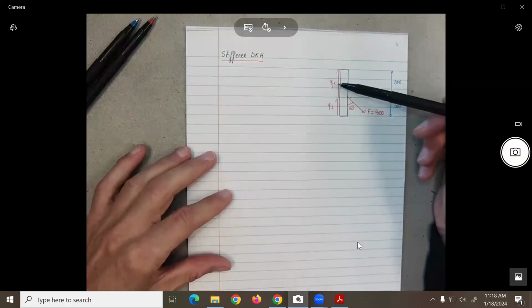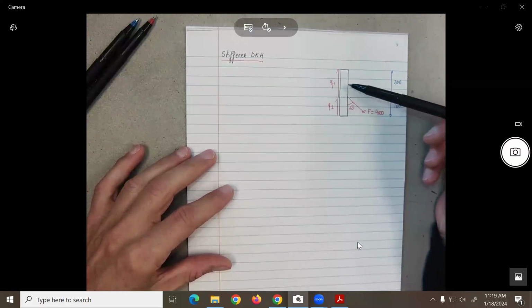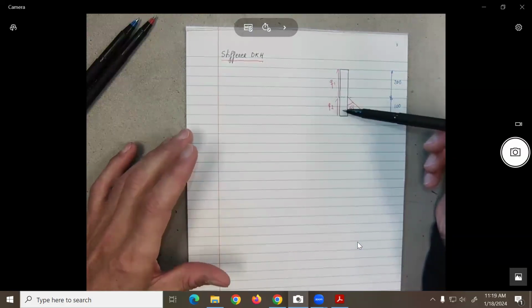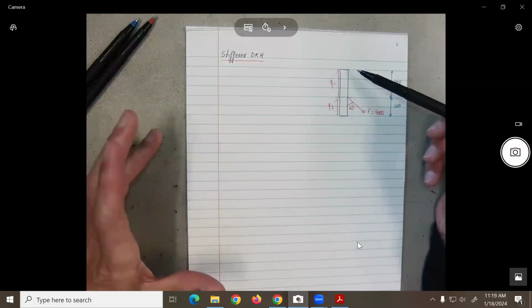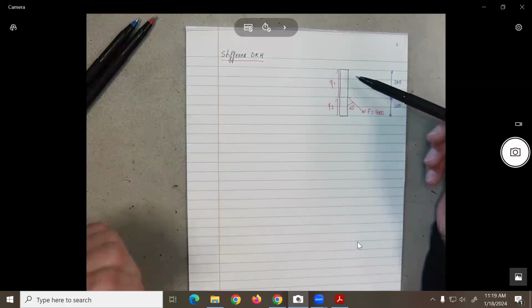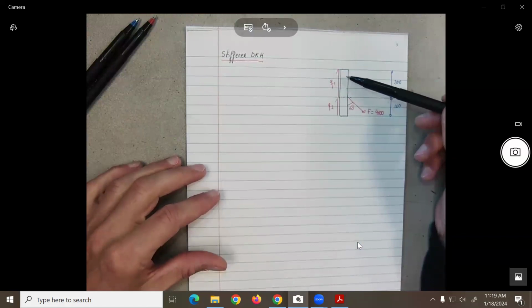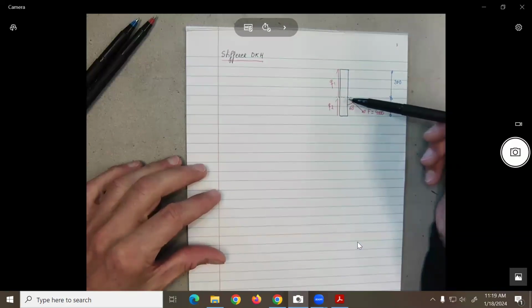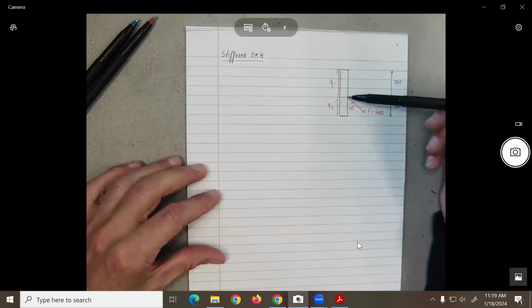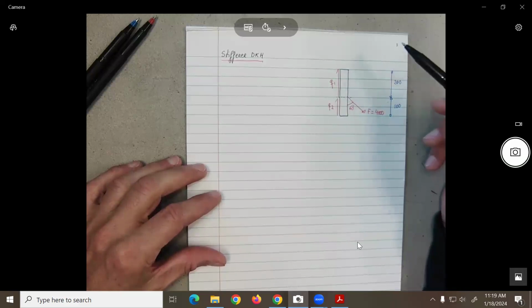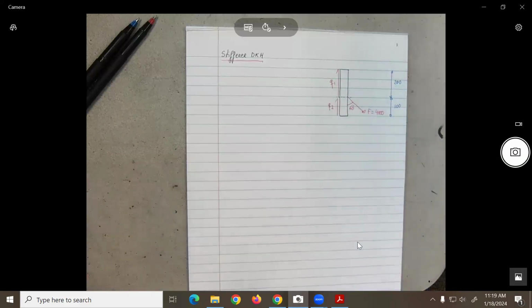You want to find the deformation in this beam, let's say of the shear force, which is what we're doing now, the bending moment. What was the rule that you learned in statics, solid mechanics? You need to make a cut every time there is a discontinuity in the loading, no? If you start from here, where is the discontinuity? Somewhere over here, so we need to make a cut before the discontinuity. So at least one or two cuts we need to do.